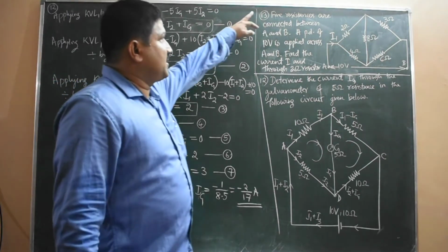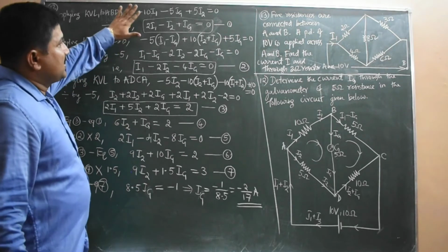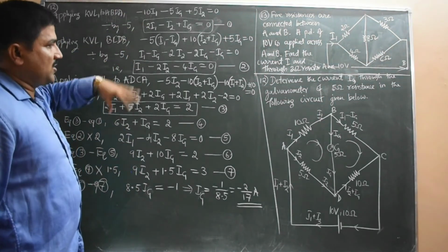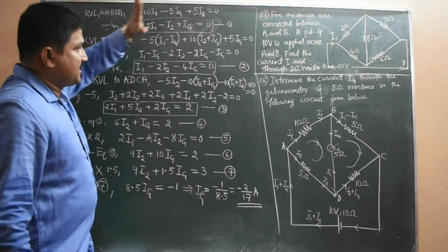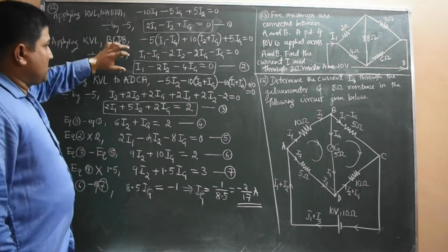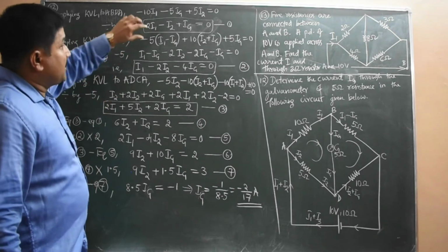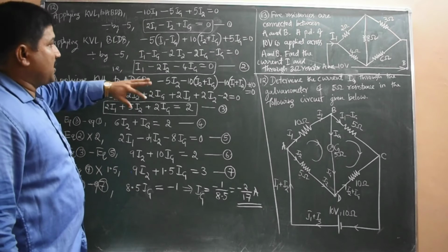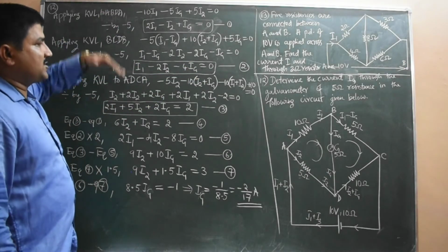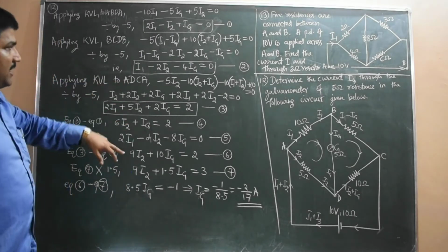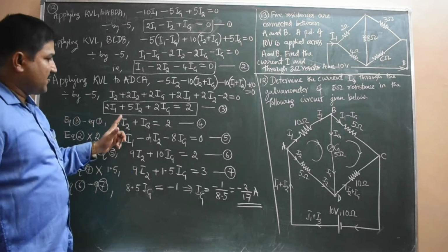Now another problem, number 13. Next problem I'll solve. So the logic is very simple here. Use Kirchhoff's loop rule. So here we have to eliminate I1 and I2 to get Ig. That's the criteria. So I1 we can cancel by subtraction straight away, equations 1 and 3. But solving again one more equation using the second equation, and with the 1 or 3, we can simplify. Again eliminate I1. Okay, then we get the equation in terms of I2 and Ig.